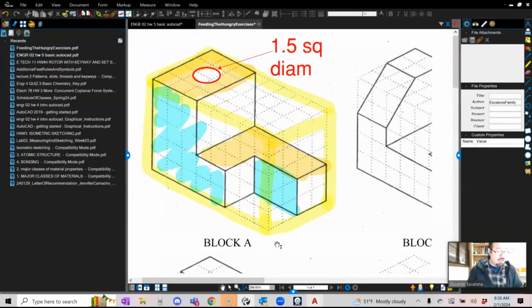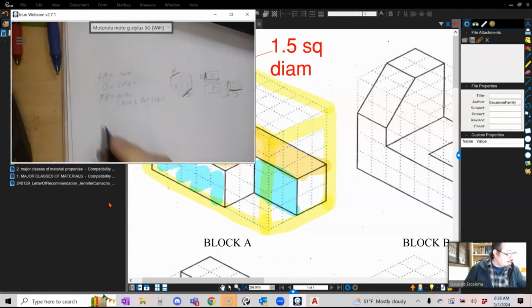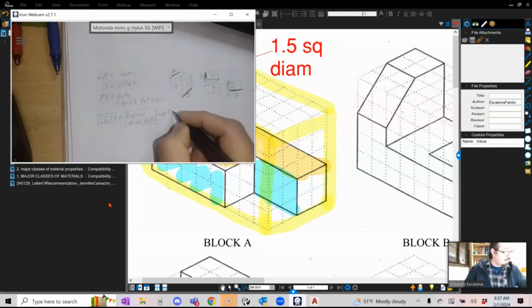By the way, if you are wondering how I did switching between screens super quick, the way you do it is by pressing Alt and Tab. And here you should try, most likely, Shift plus right-hand wheel button. This guy will give you access to the OSNAP settings, the OSNAPs and the OSNAP settings, okay?